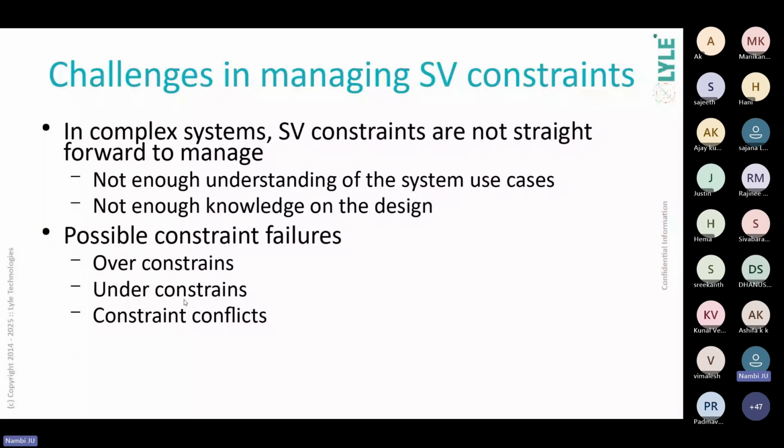In that case, the tests that are being generated may not be meaningful for the system under verification. Or you may have constraint conflicts, where in one place you have defined a constraint and you have another constraint which violates the previous one. So when you're defining SystemVerilog constraints, it is always good to have a good understanding of the system use cases and some knowledge of the design itself.